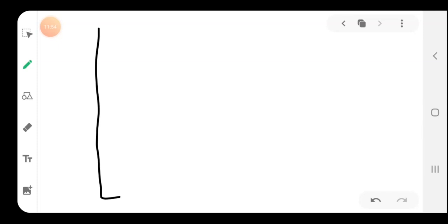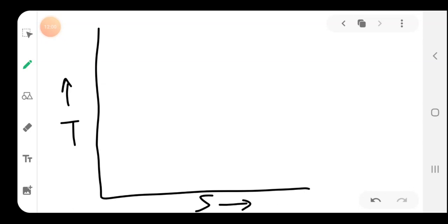Temperature entropy diagram. How can you draw these processes in a TS diagram? Suppose this is my ambient pressure, the pressure outside the aircraft. You know that this is how a constant pressure line looks like in a TS diagram. Suppose this is the inlet, position 1.